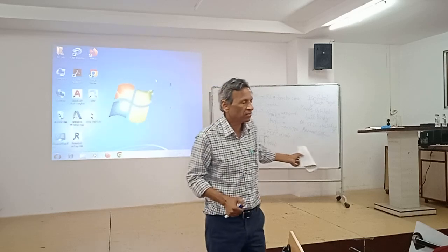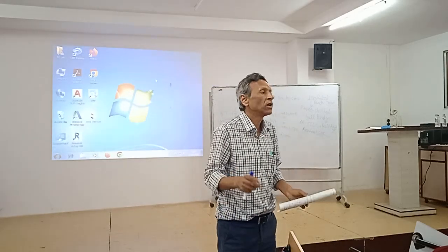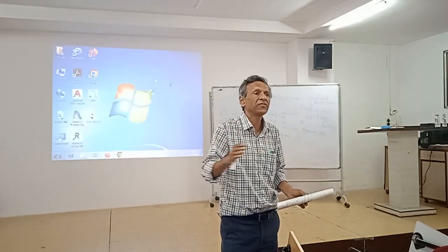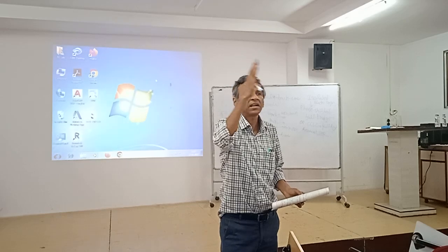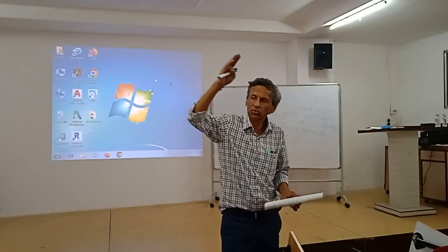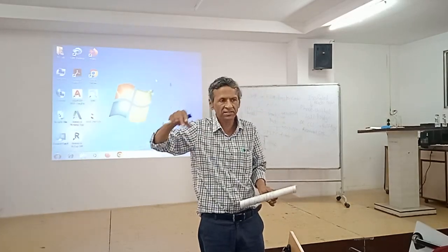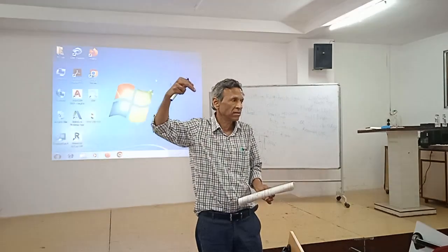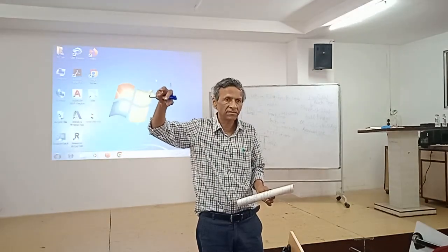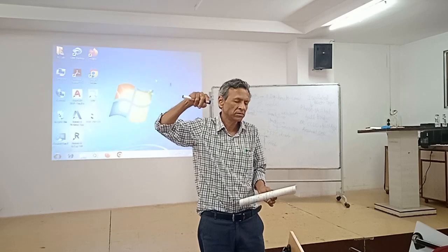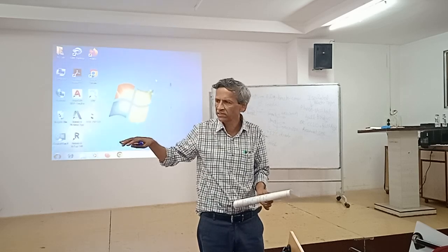And the resonant converter has a different way. You have to go for frequency modulation. So you vary the frequency around the resonant range. So you have to have a resonant frequency for L as well as C. The equation is 1 upon 2 pi square root of LC.